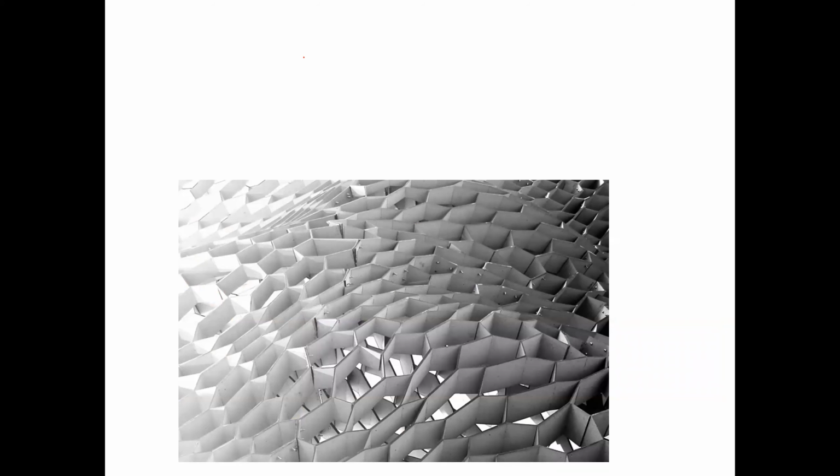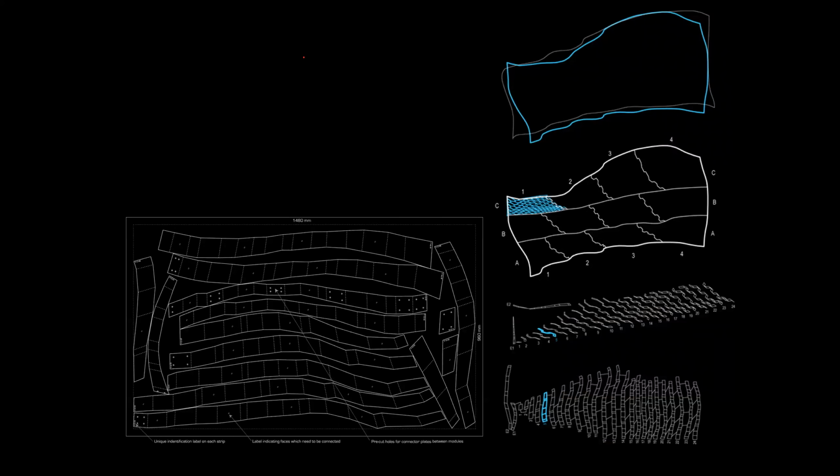And so, here's the pattern, and here was the information. So here's one of those larger walls. Break it down into panels. Each panel can then be broken up into these strips, and then each strip can be nested within whatever size the material comes in, or whatever size the laser cutter bed is. And then each one is nested, and these dashes represent the lines that were scored in order to create the folds, and then solid lines for cutting out the pieces.